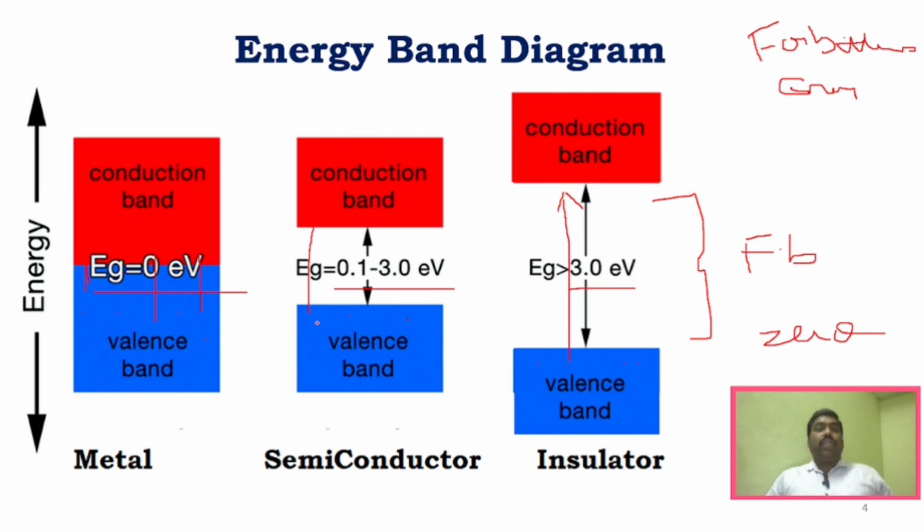And so at zero temperature, the semiconductor will not conduct any electricity. That means it will act as an insulator at zero temperature. And if you move the same semiconductor to room temperature, some electrons, not all the electrons, in the valence band can gain some energy due to the room temperature, and those electrons can reach the conduction band at room temperature and it will cause conductivity, right?